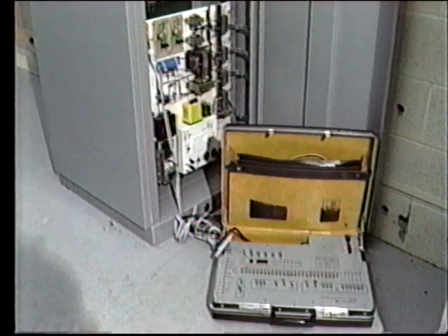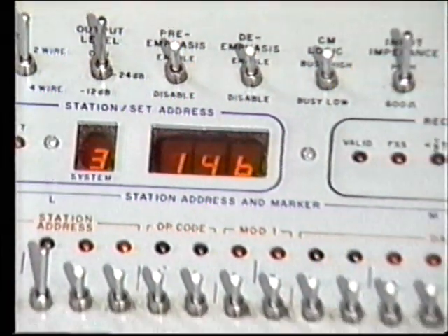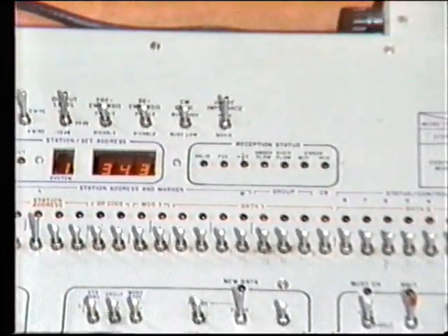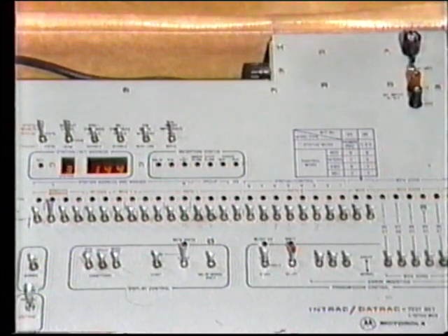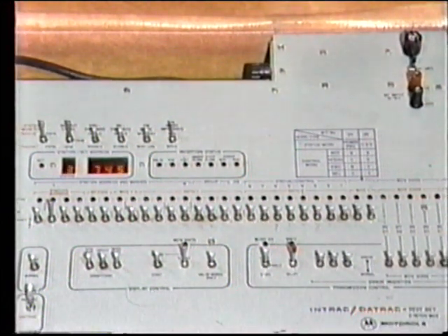Most RTU equipment suppliers provide portable test sets. These can be plugged into the RTU to function as a substitute master station in transmitting or receiving messages. Most of the tests are in the form of functional tests. A test signal is injected into different sections of the RTU, and the response is measured.